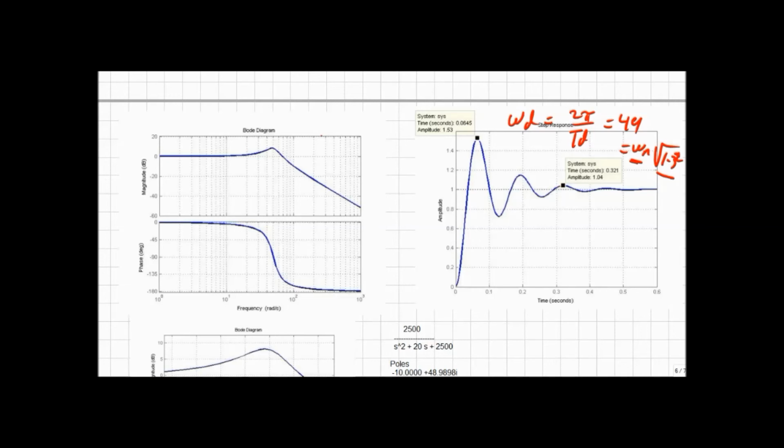So my equation for that is delta equals 1 over n, where n is the number of periods, and in this case we're going over 2 periods, times the natural log of yi minus yf, where yi is my y at the first point here, n equals 1, divided by yi plus n minus yf, which is this point here.